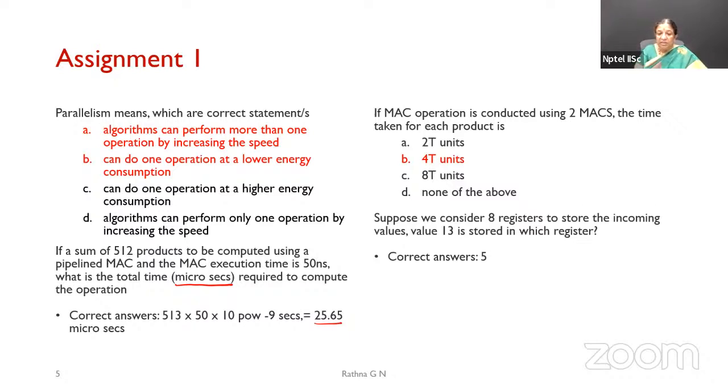So we said that after multiplication and addition, which are going in parallel, the last, if you remember, k is equal to 0 to n minus 1, x of n minus k into h of k is our computation, y of n. So the first accumulator, we have made it 0. Okay. So the accumulator will be 0, and then after multiplication, it will be adding in parallel.